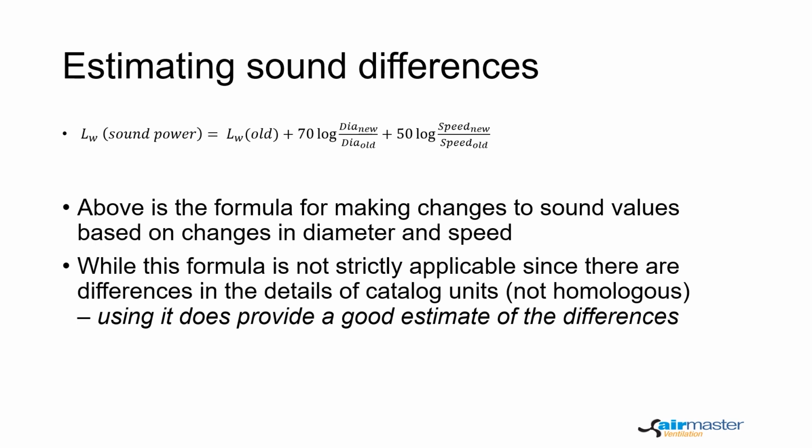However, converting from power to pressure is unfortunately a very difficult task. So what follows is comparisons of sound powers, which provides some basic guidance, but it's not really usable in establishing actual installed sound levels. Since, as noted, sound is logarithmic, then it's not surprising that in the formula for sound, logarithms of base 10 are used. This formula allows a comparison based on size and speed.